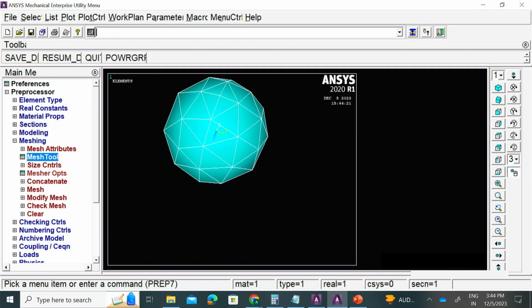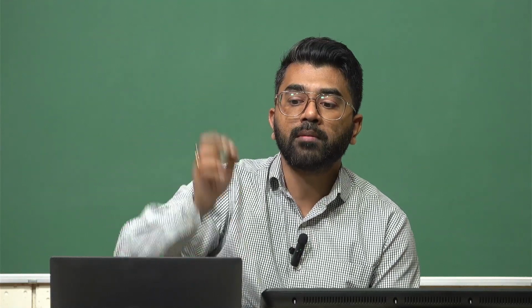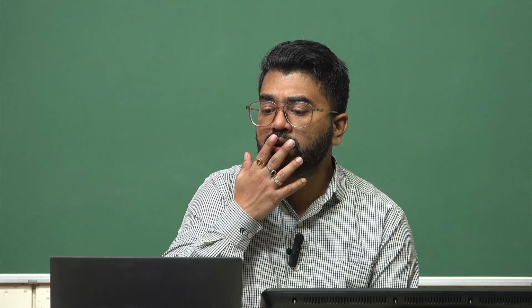but it is okay. I would like to re-emphasize our learnings on the mesh convergence study, where we want to make sure we select an optimal mesh in order to create a mesh which will not change the results. So if you change the mesh a little bit beyond this point in the number of elements, it's not going to change the results drastically, right? Not more than 5 or 10%. That's what we did in the mesh convergence study, and that needs to be applied to all the models which you study, right?